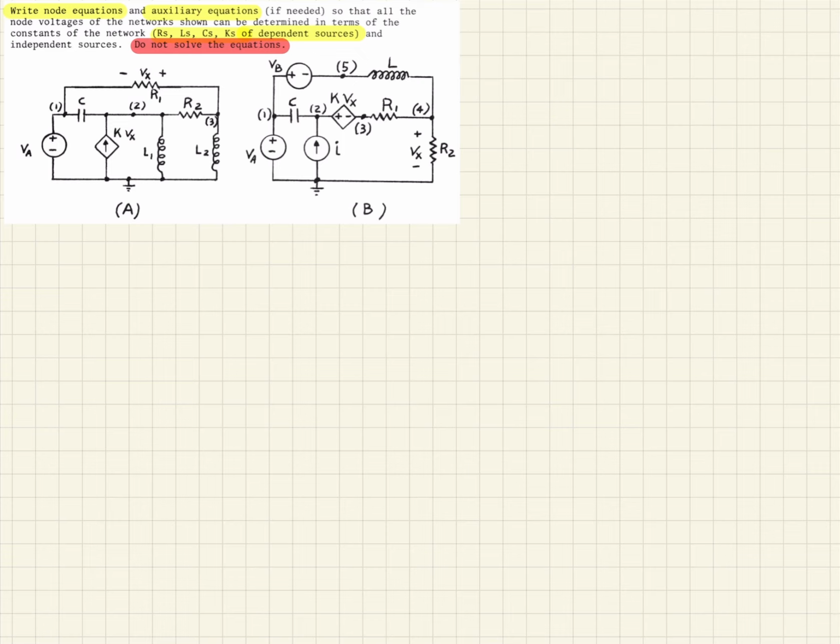So before we do that, we need to recall, since we're doing nodal analysis, that's where we sum all of the currents leaving and entering a node. Since we have nonlinear components, we need to make sure we can recall how to express that current. Of course, if we have a resistor, that's easy enough. That's just Ohm's law, simple application of the voltage over the resistance.